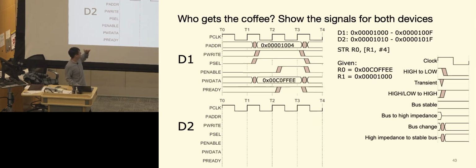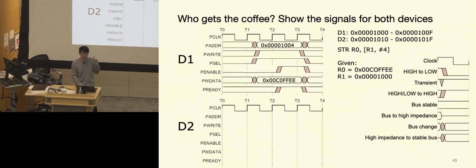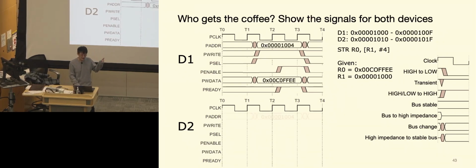You will see some other cases where, if you're trying to load something from the peripherals, that signal usually turns on much earlier because it's ready anytime there's input there. So for this case, it's the same time as the enable. So what about D2? What happened to the address? Remember they share the same address, right? So it's pretty much the same as the D1.